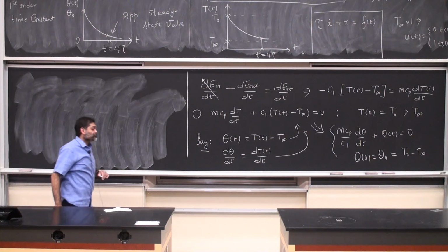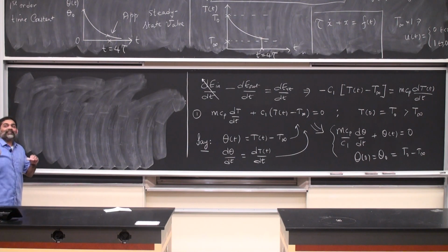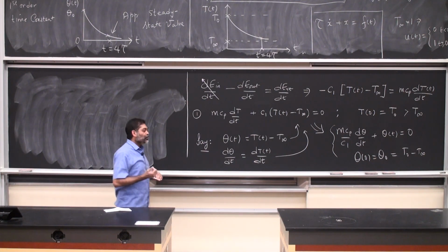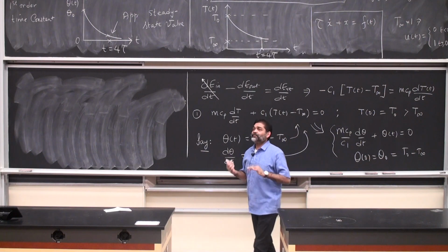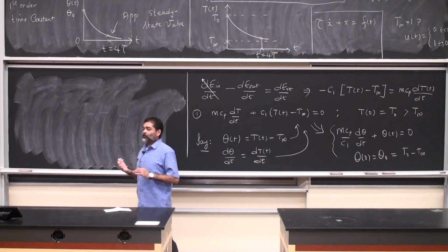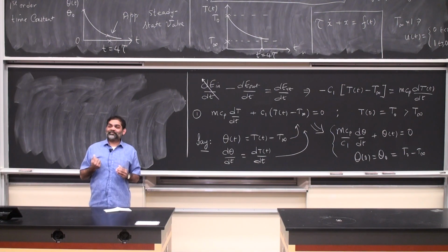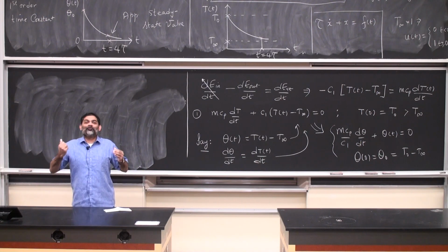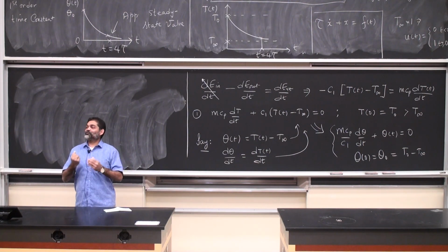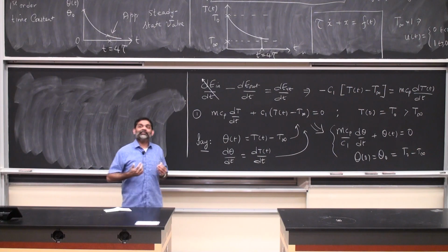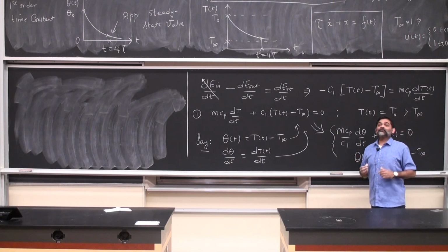I want to motivate this by means of an actual physical example as well. You've seen steel cables. I'm pretty sure all of you have seen steel cables, right? How do you manufacture steel cables? You take cylinders of steel and then you perform a heat treatment process. It is called an annealing process. If you perform an annealing process on steel, it improves its workability. You can knead it, you can make it into a dough of some sort. You press the dough more and more, it increases its workability. You can make it into long, thin rods or sheets and whatnot, right? So this process of annealing is also something that we could model using the first law of thermodynamics and bring it into a first order system.